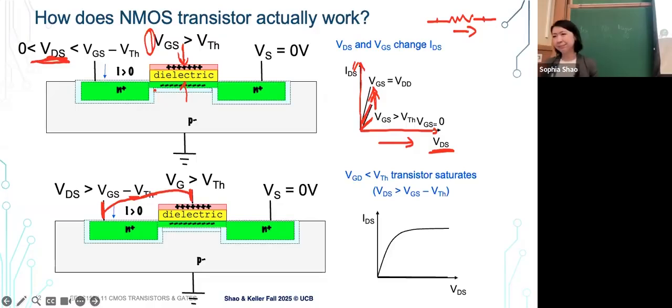The channel width doesn't really grow anymore. So basically you don't get any benefit from a higher voltage. Right, at a very high level, exactly as Ryan said. When the voltage difference between those two terminals gets close enough, near the gate and the drain part of the transistor, you create what people call the pinch-off region. It's where things are sort of saturating. The channel doesn't get wider. It's like a fixed channel no matter how high a voltage you're applying. That's always the fixed channel that you need to go through.